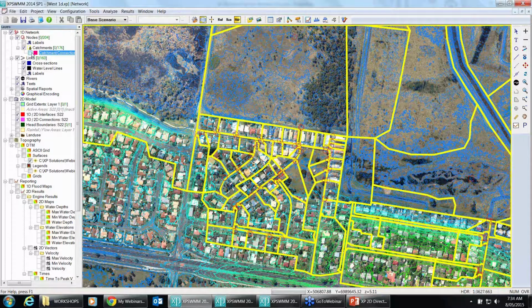Conversely, if we were to move to a direct rainfall method, we wouldn't go through this process at all. We would simply identify the major catchment boundary if we're going to do a complete catchment direct rainfall model. Some people will ask whether we need to extend our model beyond those upper catchment boundaries. Sometimes that can be useful, to take care of any major inter-catchment or cross-catchment flows. But generally speaking, covering the whole catchment is good enough.